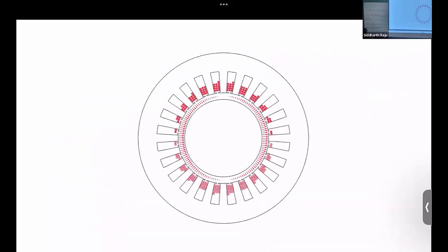So this is what the H field will look like if we had just one phase alone, HA of theta at any particular given time. Well, can you tell me, guess what it will look like if I increase the number of poles? Let's say this is a two-pole motor. Because if you look at the H field, there is H field coming out, H field going in. So I can call this the north phase, this the south phase. So effectively, it just represents a two-pole motor, right?